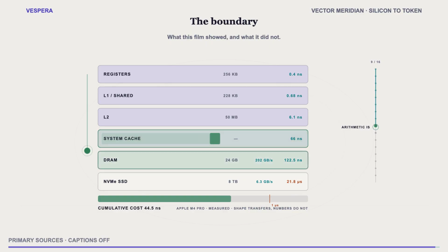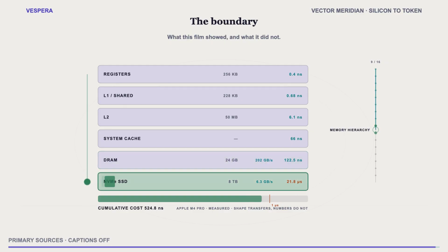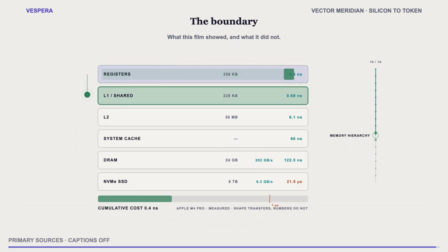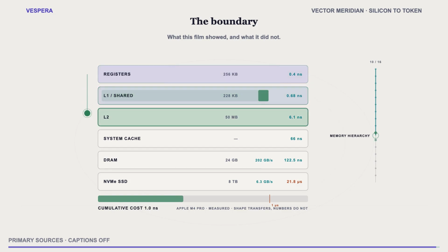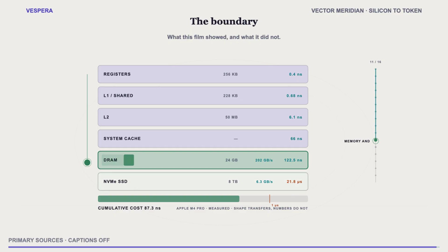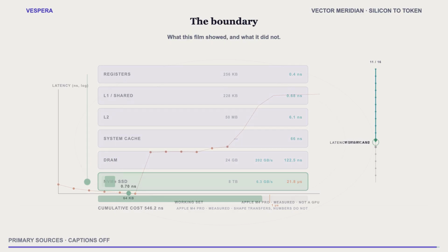We simplified. Real serving is heterogeneous and bursty. Real training runs use combinations of techniques we described separately. The arithmetic intensity of 1 for decode assumes dense attention and ignores the KV cache traffic, which at long context is not negligible. Every clean number in this film is cleaner than reality. And we did not cover power delivery, cooling, chip fabrication and yield, the economics of foundry capacity, networking hardware in any depth, compilers, or the enormous body of kernel-level optimization that makes any of this run. Each is a film.